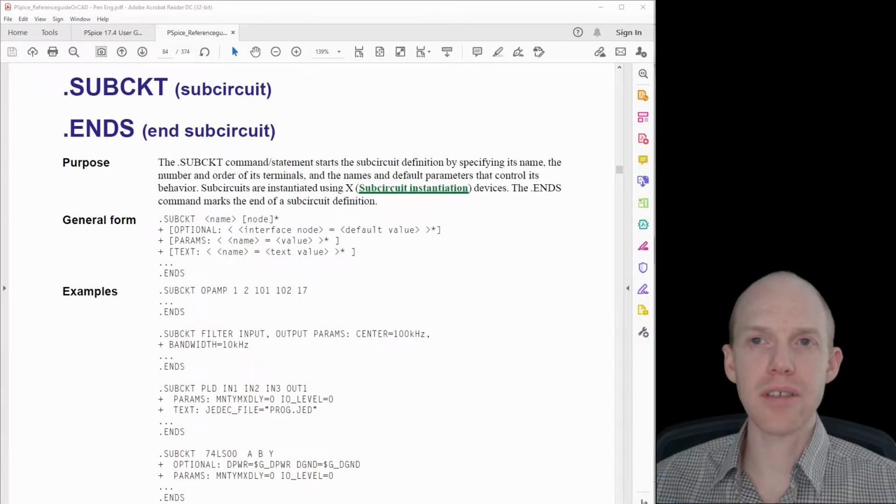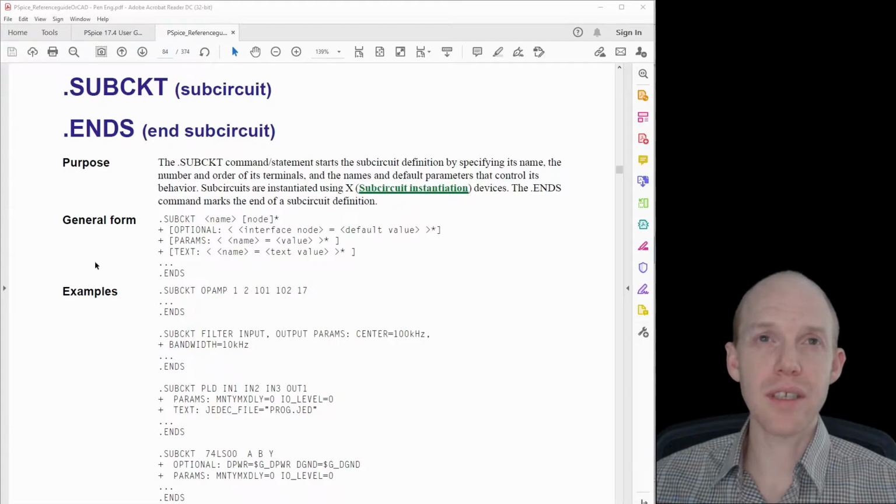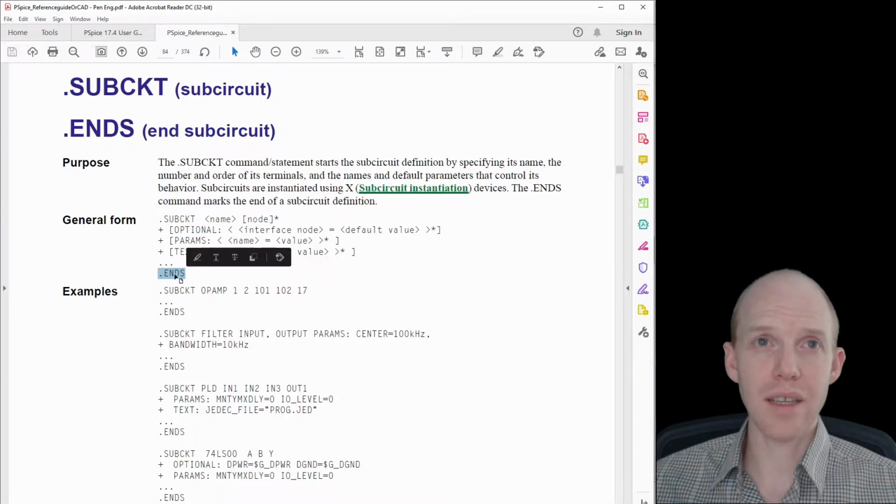Then once you get all your elementary parts down, you can wrap them in a subcircuit. And that's a way of avoiding redundancy or making a higher level type of part, like an opamp. It's a good example. You can have a subcircuit that represents the whole opamp, and then you can use it in multiple different places in your larger circuit. So the subcircuit starts with this .SUBCKT parameter, and then it ends with this .ends parameter.